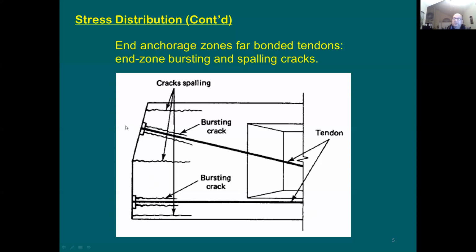Also, imagine that you put here a loss of pressure. What's going to happen to the concrete? Now the concrete wants to open up, as if you have a kind of a wedge that you push throughout the concrete. Now this wants to open up and down. This is why you should expect to have here some spalling cracks. Again, the best option here and the best way to treat this is to provide vertical ties or stirrups. Also around the bar itself, if you like, you can provide here a spiral reinforcement. It's going to be very close to the strand itself.